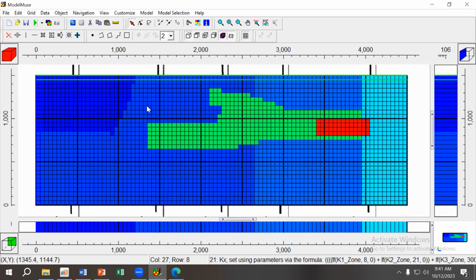Other than that, this is a groundwater divide. So this is a no-flow boundary. This is a flow direction. So this is a no-flow boundary, no-flow boundary. And the bottom of the aquifer here is also another no-flow boundary. Okay. So let's just add these.